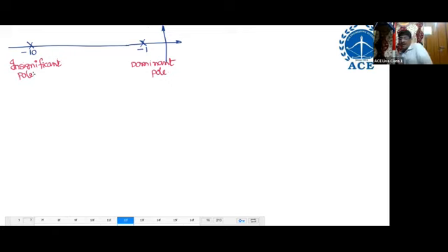We cannot call all the leftmost poles insignificant. There is a condition. The insignificant pole time constant must be less than or equal to the dominant pole time constant divided by 5.